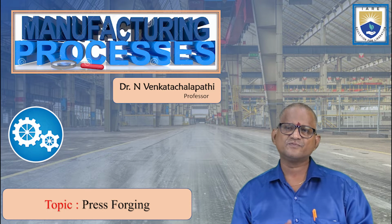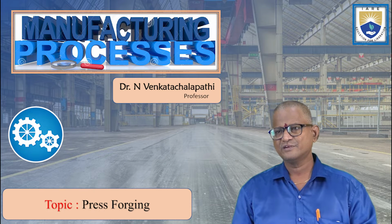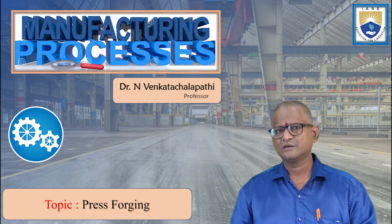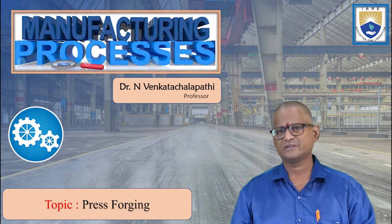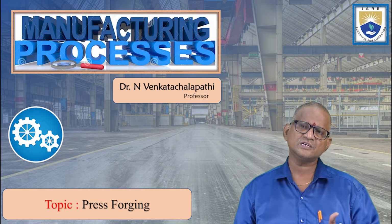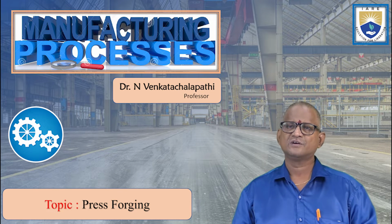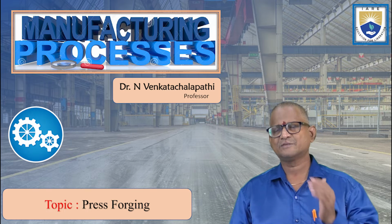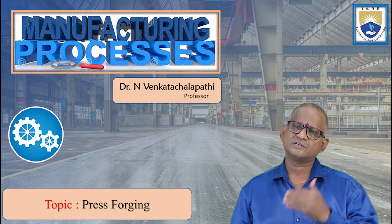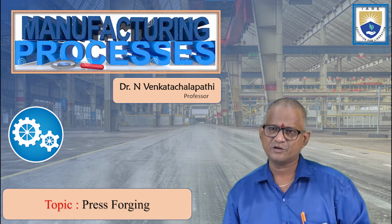Press forging can be defined as the process of changing shape and size by plastic deformation of heated metal. Forging can be either hot forging or cold forging. When metals are heated above their recrystallization temperature, we call it hot forging. When the metal is worked at room temperature, we call it a cold forging operation.